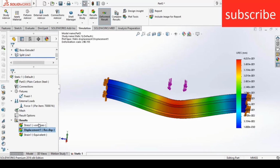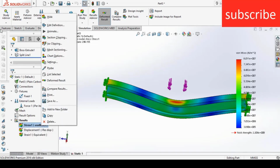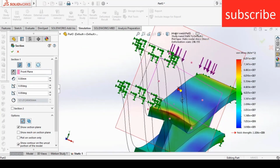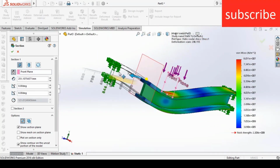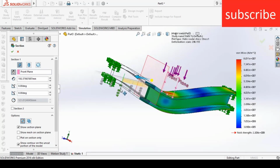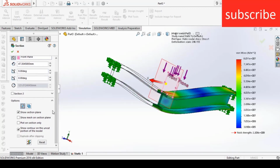Now click on stop. After that, go to stress simulation, click on show. Now right click on it, click on section clipping. So here you can see I select a section and you can see where the load acts. You can select this section of the plane as per your requirement. Either you click on the arrow or choose the section where you want to see the stress in the beam at a particular point of length or width. It's quite handy, and you can take the photos from here and use them in your simulation analysis,